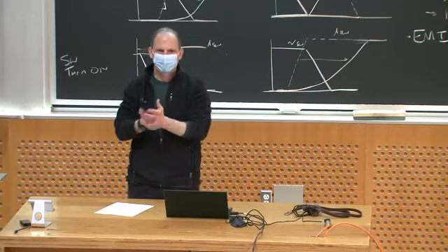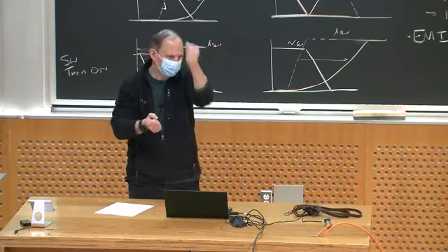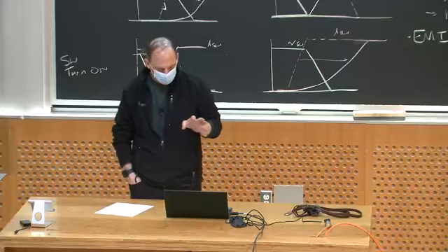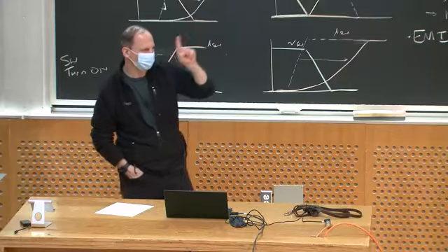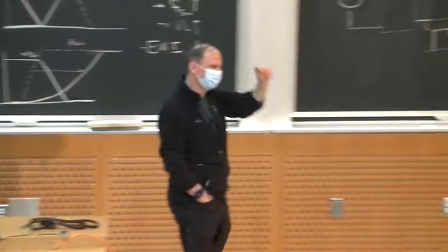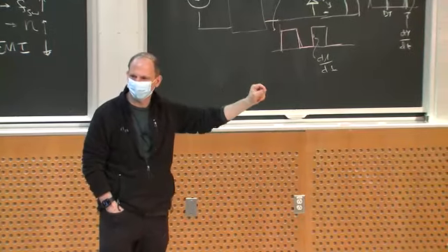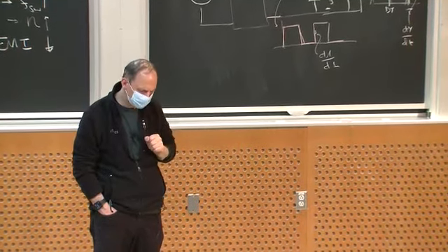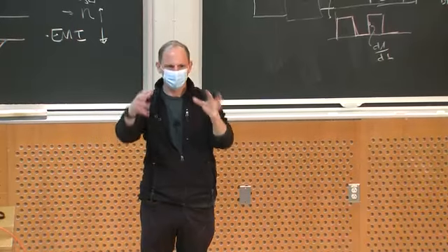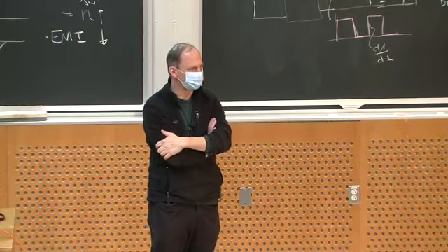You can't just generate switching angles at your command, because everything's governed by what the ripple current in that resonant inductor is doing, right? So this is nice in that it lets you generate a low frequency component plus high frequency into an output and get filtered and get what you want, but it's very constrained in how you have to operate it. It's in that first category of converters I talked about.